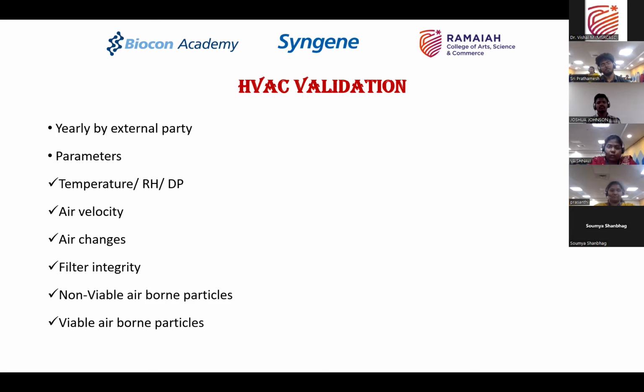Filter integrity means what? The HEPA filters. Can anybody elaborate on HEPA filters? What is meant by HEPA filters? High efficiency particulate air filters. In laminar airflows, or the areas where sterile air has to be used, all these areas will be equipped with HEPA filters.